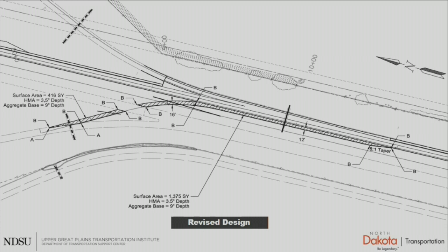It's also probably worth mentioning that the current ramp connections that we use are utilizing a paved surface, but based on things like the type of vehicles that are using the ramps or the interchange or that area of the interstate, and the volumes of those types of vehicles as well, there could be different cost savings realized in addition, depending on whether we used paved surfaces or not. Paved surfaces we'd find on higher ADT roads, larger vehicles, whereas for other types of ramp connections, there may be potential for using full depth aggregate instead. And that's obviously reserved for situations where we've got lower traffic volume, lower ADT, smaller vehicles, things like that.